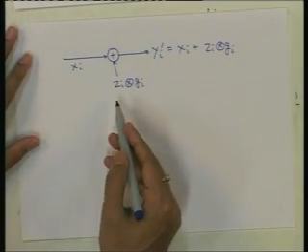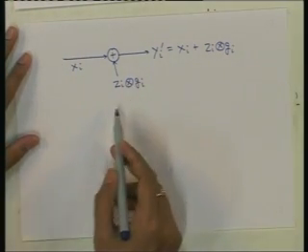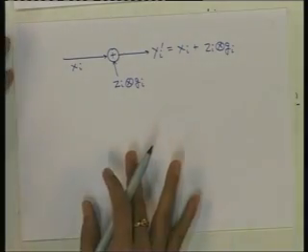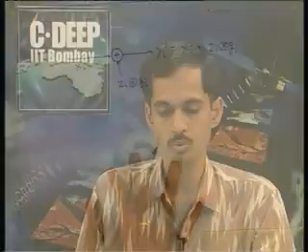And just like this, we can also convert any additive Gaussian noise channel with colored noise into a linear filter channel also. So, what we have to do is put a so called whitening filter at the receiver, which will make the noise white.